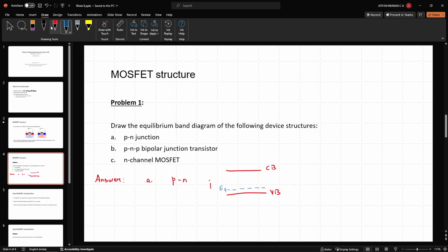And similarly, we have the N-type device. Now again, all standard assumptions apply here. We assume it is the same material, so it is not like two different semiconductors are used. We'll just assume that it's the same substrate all across and just the doping changes in these two regions. I'm saying that because the band gap will remain the same across the device. The energy gap between the conduction and valence band is not going to change.